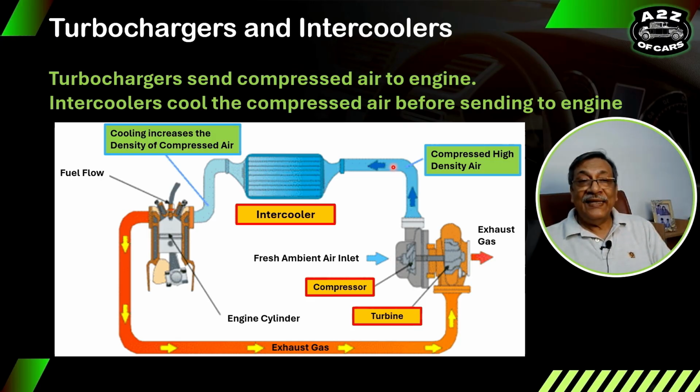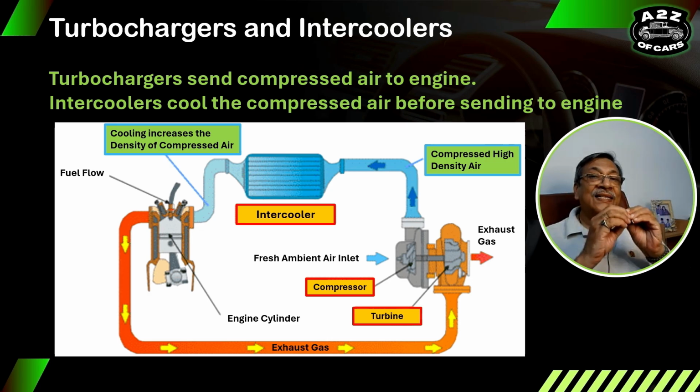Now this highly dense compressed air, which has lost some of its density because of getting hot, is pushed through the intercooler, which cools it down, increases the density of the air, and then pushes it inside the cylinder. So now instead of the normal atmospheric pressure air, you have highly dense compressed air inside the cylinder.